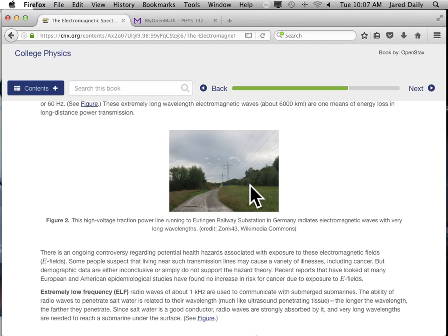And those frequencies on either side of the main frequency are vibrating back and forth in frequency. So the frequency is changing a little bit on those side bands. And that vibration of those sideband frequencies gives you left channel and right channel for stereo sound. Both of them are carrying the actual sound that's being carried by the radio. So those frequencies correspond to the audio frequencies that are carried.